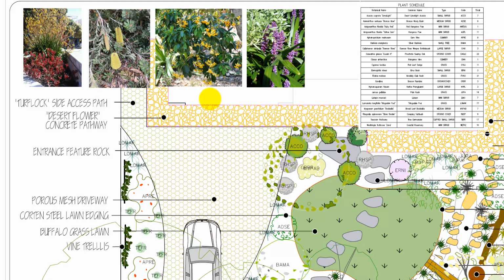But in this case, we will be able to edit the title block and say 1-50, but do include A2 sheet. That means if someone picks this PDF file, they are assuming you're going to print directly to an A2 sheet. You can, of course, print PDFs on any size sheet of paper. So incorporating the scale and that statement covers all the bases.